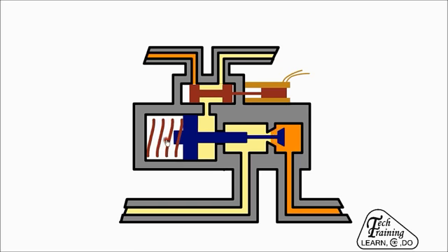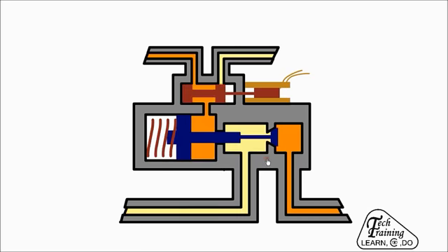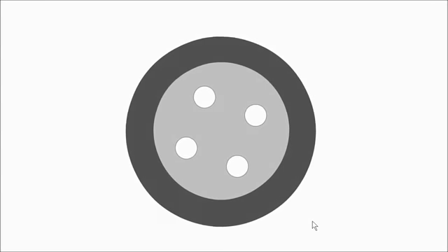The spring force opens the valves and the additional rod volume also increases the fluid pressure and reapplies the brakes. This cycle can happen 20 times per second and results in the pulsing sensation in the brake pedal. ABS pulses the brakes on and off. It prevents the wheels from locking. The car will stop in a shorter distance and it can be steered.